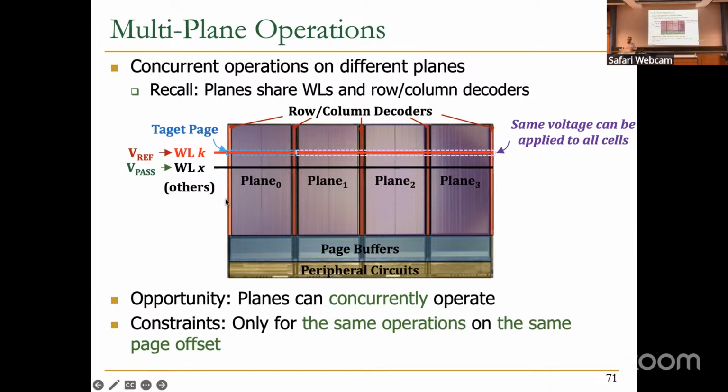So the controller needs to understand that we need to address several reads, and these reads are going to the same die, different planes, and all of them can be addressed by multiplane operations. Then when the controller sends the request to the NAND flash chip, it sends multiplane operations. It can be for read and write also. It doesn't need to be only for read.